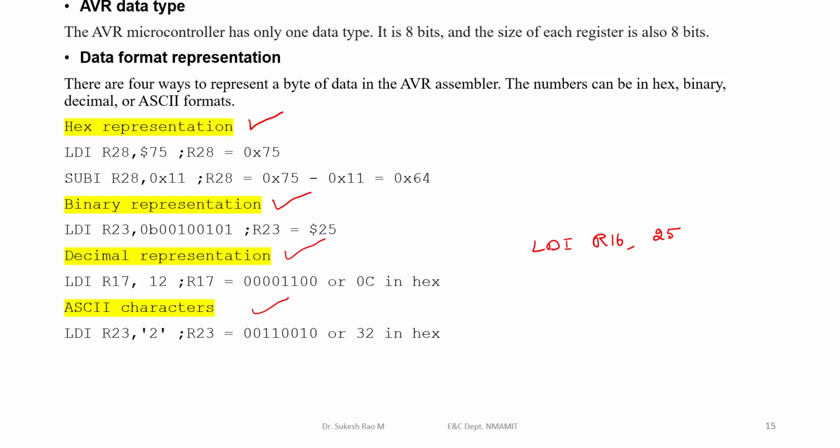If I specifically want hex number 25, then I am supposed to write 0x25. 0x25 is not equal to 25. 0x25 is 0010 0101, whereas this 25 is the decimal 25. To calculate, 16 is the next place, so I write 1, then 1 0 0 1 in the 8-bit fashion.